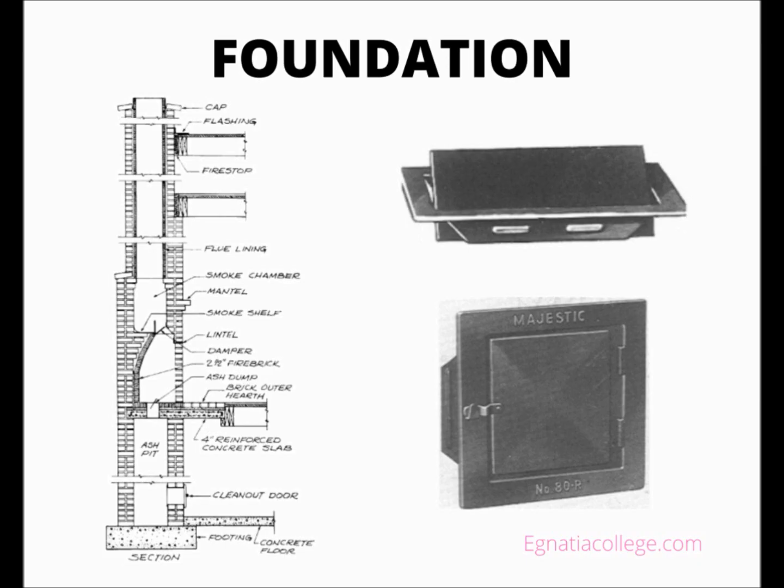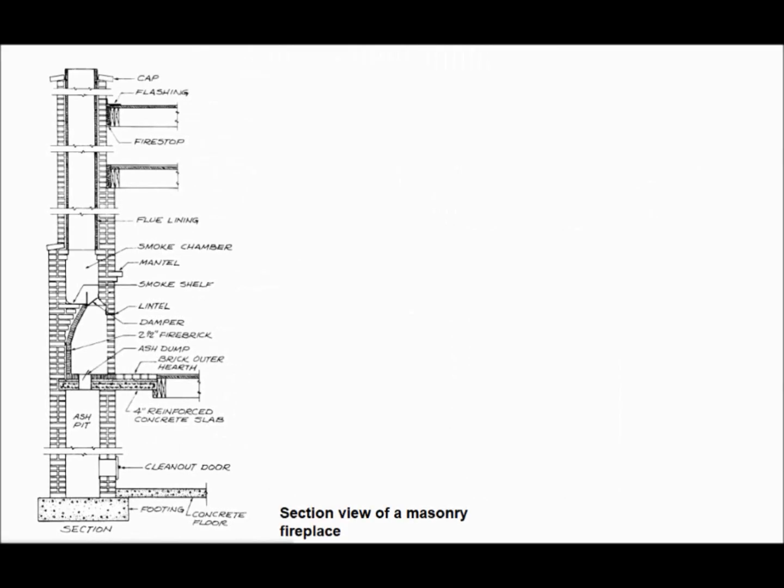The ash pit is a reservoir to hold ashes that are dropped through an ash dump, a small door in the floor of the fireplace. When the foundation includes an ash pit, a clean-out door is installed near the bottom of the ash pit.